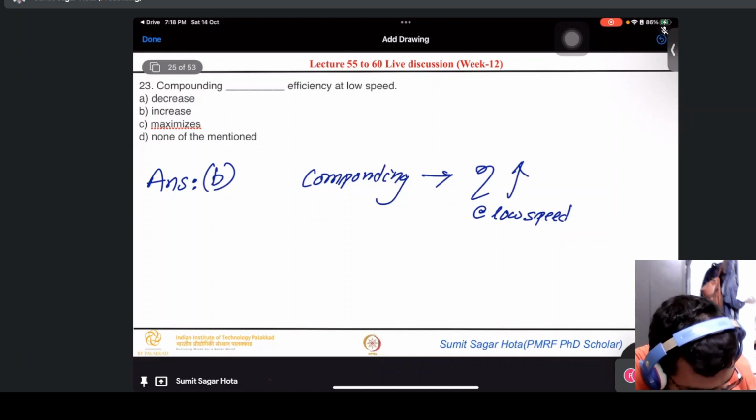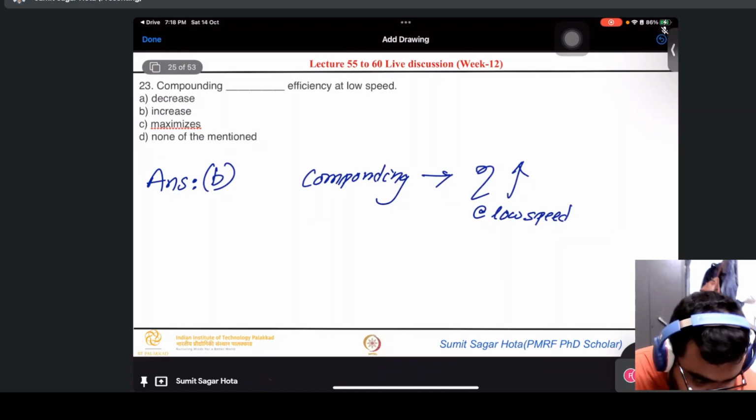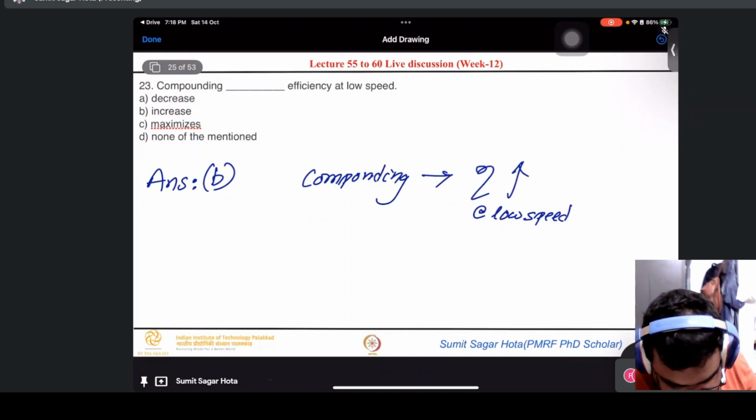It's not like for high speed flow you will have only two stages. It depends on the size of the turbine, its rotor diameter, everything. Lots of factors are there, so staging also matters. For example, for very high speed flow, you have to increase the number of stages to increase the efficiency.